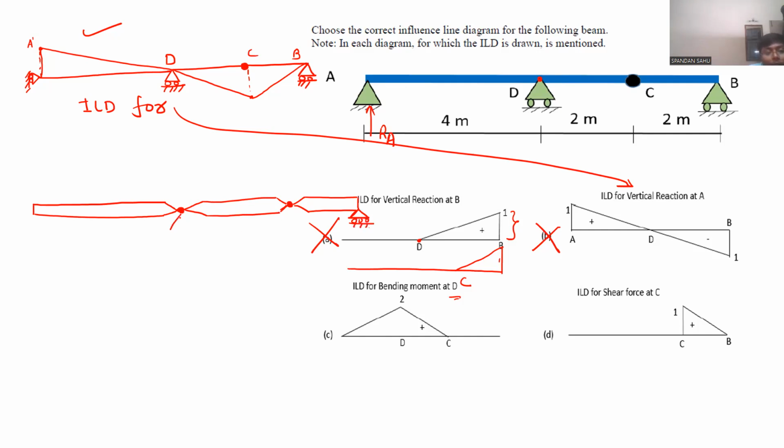And there is one more hinge also. Now, we have removed our stress function by applying a bending release. Now, we will give rotation in positive sense, and this is the positive sense at a section for bending moment, that is sagging.